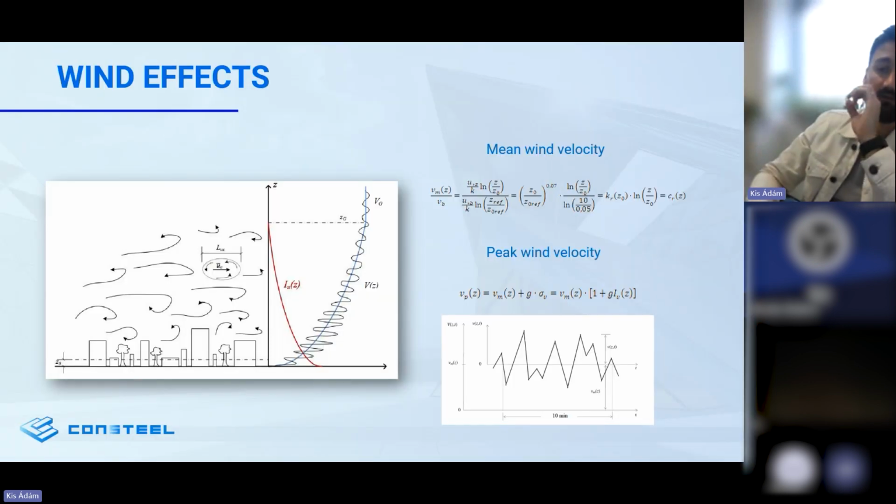So let's dive into a few topics and actually just repeat a few basic assumptions that we are all familiar with. When it comes to wind loads, the standards usually assume an atmospheric boundary layer where the wind consists of 2 parts. The one is a stagnant mean velocity term, which is VM from the standard, and it is defined according to a terrain category from that table from the Eurocode.